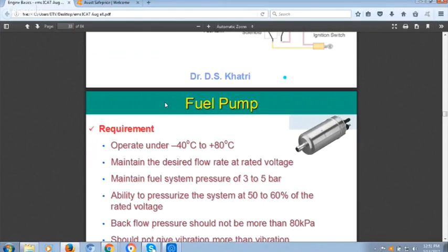And many cars were standing on roads. There are a lot of challenges. What happens? Because the technology is designed somewhere else, keeping in mind the environmental conditions of that particular country. So Hyundai, they have designed as per Korea or Japan. So the pump which they have designed is capable to withstand around 55 degrees Celsius temperature. In India in summer, the temperature goes up to 65 in the fuel tank. The pump fails.